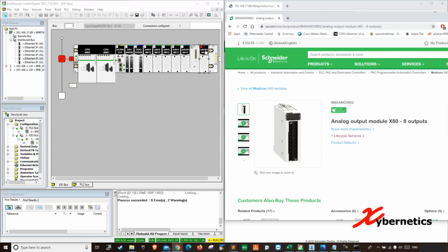With the AHO card here, you have to be aware of a bit about network settings and cybersecurity, because all the data are being exchanged through Ethernet. So for example, what I did was that I hooked up this controls network to the corporate network, and the corporate network naturally had a DHCP server, and my M580 has a DHCP server. So both of those servers were fighting with each other to assign IP addresses.